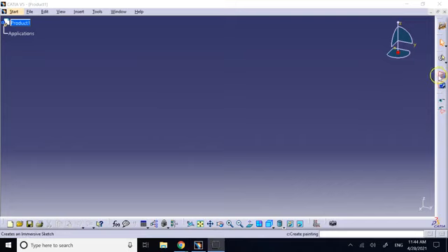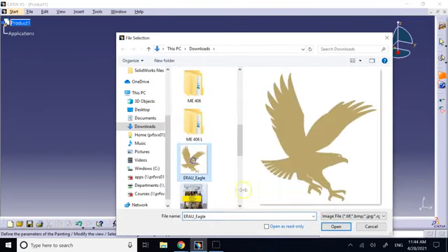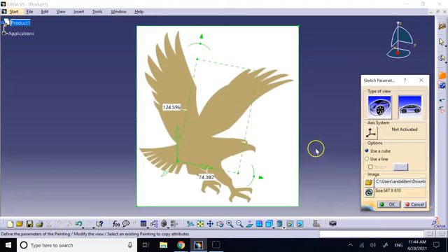Here you are going to click on Create an Immersive Sketch. You click here and it allows you to go and get your image. So here we go, get it. Now you see the axes are not exactly the way I want. I want this picture to be on the background plane, like a front plane. So I want two of these axes to be aligned X and Y, and this one perpendicular to the plane. Right now it is not.